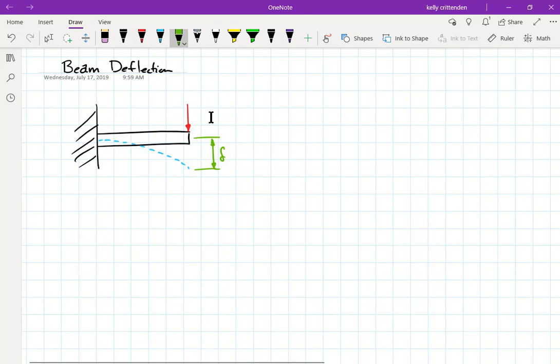So we'll actually have an equation for this line. Equation of the elastic curve. So we do make some assumptions in there. The elastic curve, so it stays in the elastic region, so that we haven't permanently deformed anything. Once we start yielding the beam, then these equations kind of break down a little bit because they depend on modulus of elasticity, which is not linear outside of that elastic region.